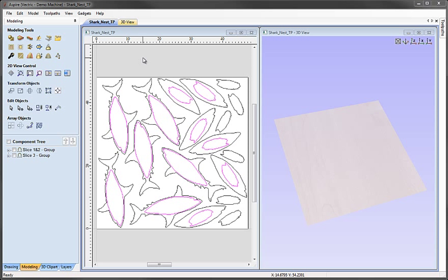The other edit I want to make to the vectors is to make sure the tool has enough room in order to fit down the sides of the part. Normally we'd do this by using the boundary vector offset in the toolpath form itself, but in this case I don't want to offset the top edge, I only want to offset the bottom edge. That way the centre of the tool will just roll up to the top edge, but then if we offset this bottom one, the centre of the tool will be able to go past and make sure that the side of the tool machines all the way down the side of our 3D components.